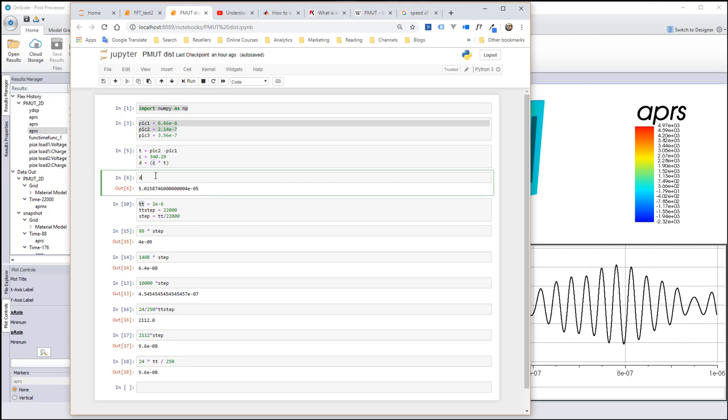And you have to divide this distance by 2 because you have a back and forth of the wave, right? So this is 2 times the actual distance to reach the obstacle. So if you want to know the distance from your sensor to the obstacle, just use this simple formula and you get the distance. So I'm doing all of that just to explain to you how it works.